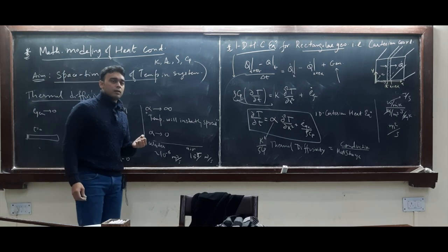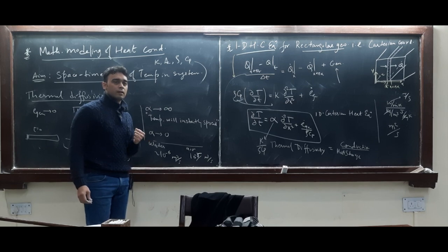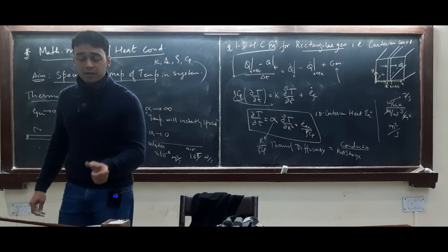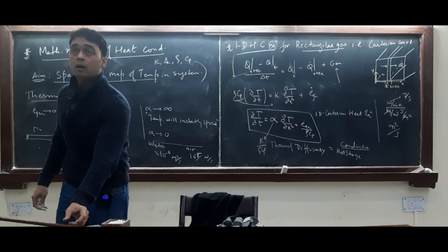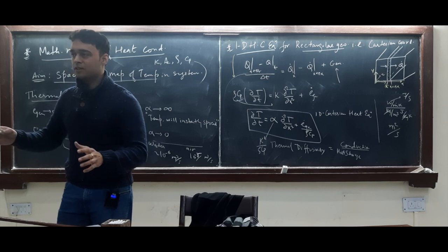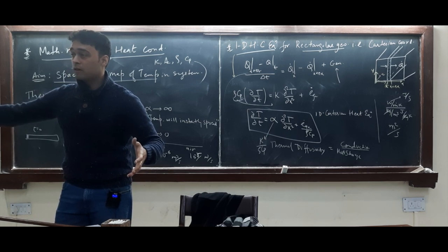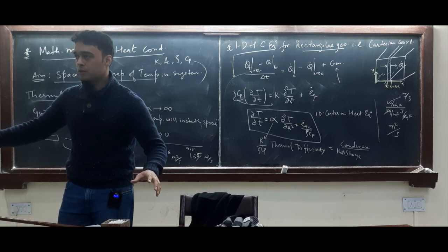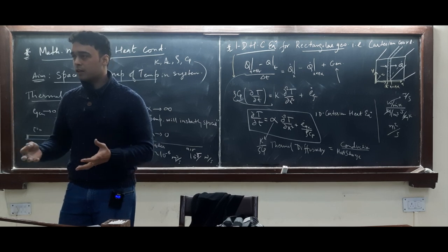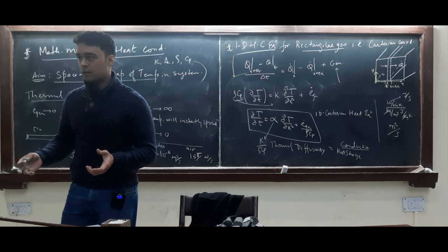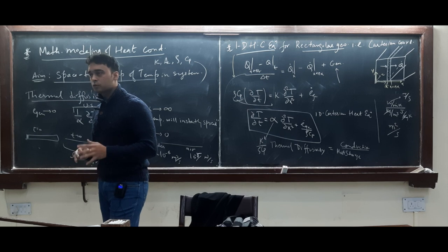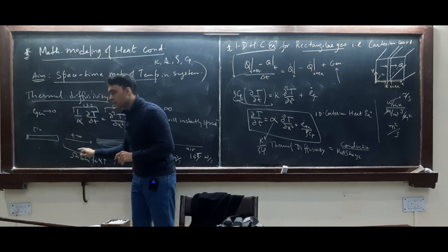It is just a relative value. Relative to what? So, I'll give you something to think about. Would temperature spread faster if I made this rod smaller? If I made this rod 1 kilometer long, here I gave 100 and the entire rod is at room temperature. It will take longer, naturally, to spread it, to reach the other end or to spread throughout. Yeah, the throughout time. So we are associating alpha with this time.